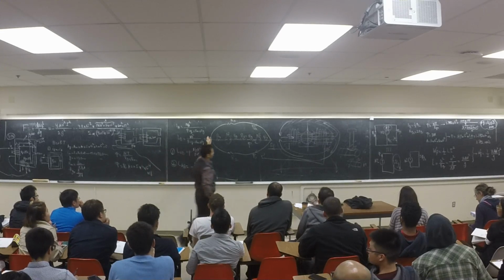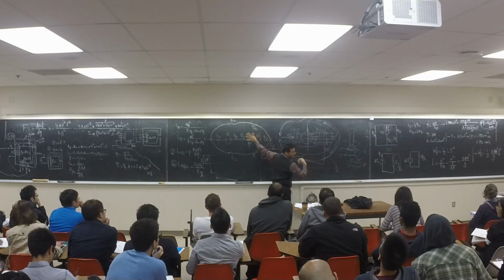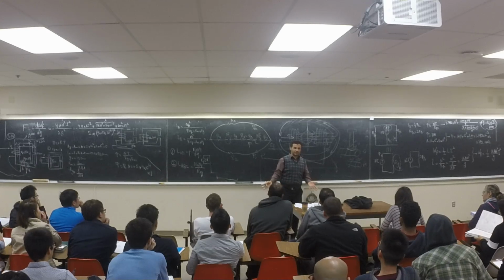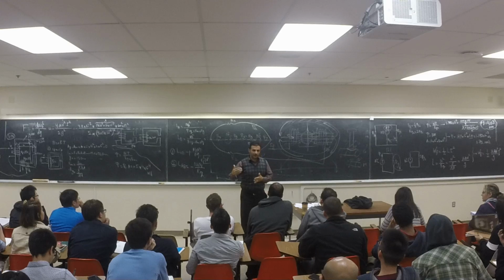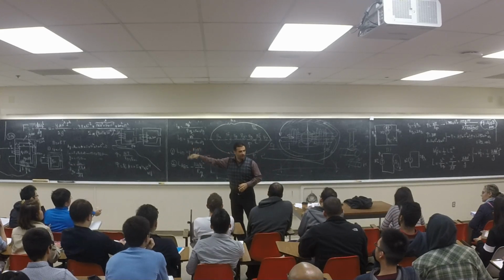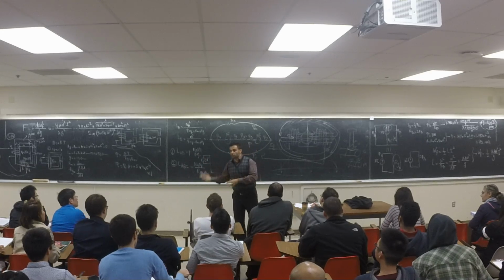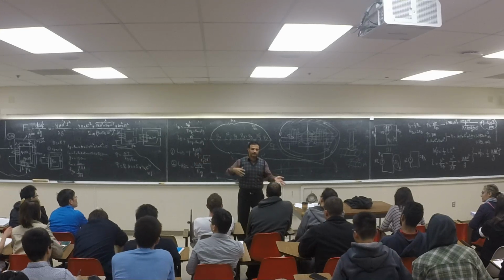But this is a magnetic circuit, what we talked about. This is a real motor, and it has this magnetic circuit, and we can calculate the flux. We design this machine, this is all the design part. You say I'm going to use this kind of material, so the B shouldn't be more than 1.4. You calculate the number of turns and those kind of things to make sure you're avoiding saturation. I wanted this much torque, so you can calculate that: if you put this many turns, you're going to get this much torque. This is all the design part.